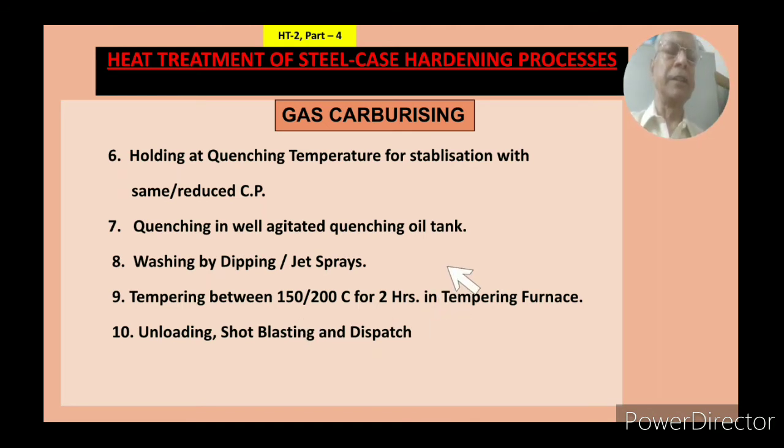Okay. Here I will tell you something about quenching. In case of quenching, both the quenching temperature as well as the oil temperature, or total oil tank conditions, you have to maintain proper agitation. It has to be all around. It's not one-sided. Sometimes fans are situated down below at only one side. It is not desired. You have to place them on both sides so the agitation is total. Then heat transfer through recuperators is also required.